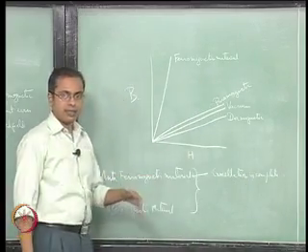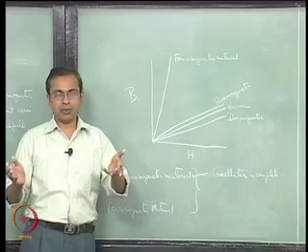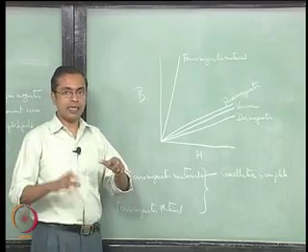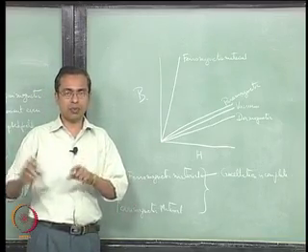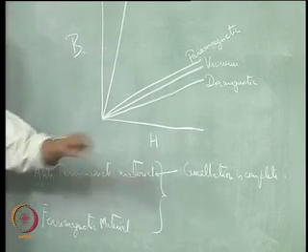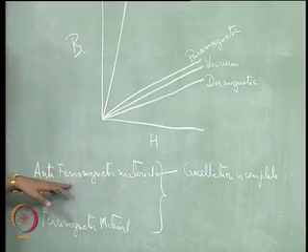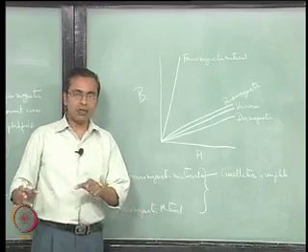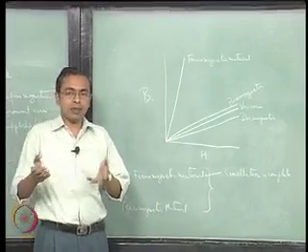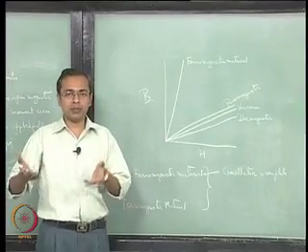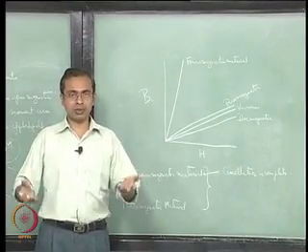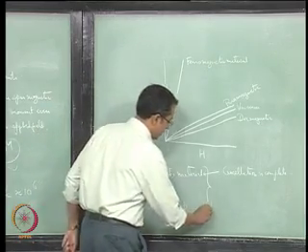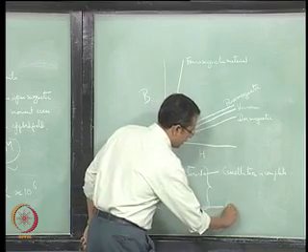Okay, so if the atoms are of the same kind and you have the same number of atoms and the same valency, all those things are the same, and they were aligning themselves in opposition in a cooperative manner, they will all cancel out and you would get an antiferromagnetic material, which is where the cancellation is complete. On the other hand, you can also have this kind of coupling, except that the cancellation may not be complete because maybe the neighboring atoms are of a different kind, or of a different valency and so on. And so you will still be left with some net magnetic moment, and that is the ferrimagnetic material. Cancellation incomplete.